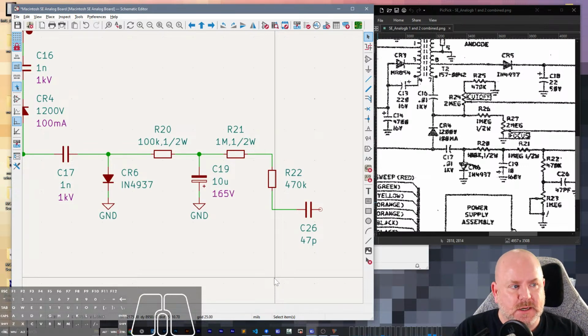But the bismuth solder, if you're doing repair work on a board with leaded solder, is absolutely fantastic, because the interaction of lead and bismuth reduces the melting point. Especially for a vintage repair, you need way less heat to work on it.